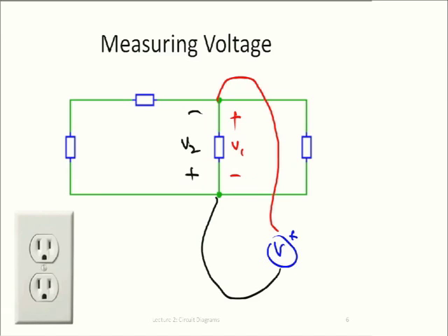No, it would simply measure 110 volts, that's all. Actually the better ones would measure 110 volts, and the cheap ones depends on how it's set. But generally, voltmeters can measure pretty high voltages, typically sort of 1,000 volts, so it doesn't break. You're in danger way before the voltmeter is in danger.